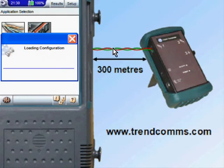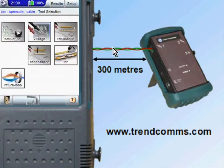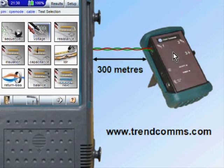In this demonstration of MPCopper, we will measure some of the parameters of this short cable between the MultiPro and its remote transponder. There are many individual tests in the cable application. There are simple multimeter tests such as voltage, resistance, insulation and capacitance. There is a TDR for measuring line length and locating faults.